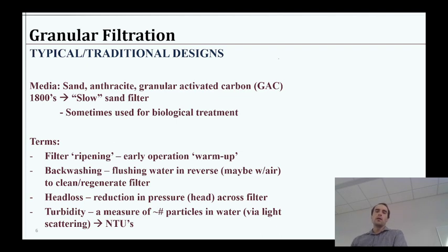So what we are learning about today, this granular filtration, we would call rapid sand filtration. So you'll see that kind of terminology a lot. That just means we're continuously loading water on. The water's going to make its way through pretty quick, and we're grabbing those particles like we described, rather than letting it have enough time for a biological process to consume waste products and junk that's in the water.